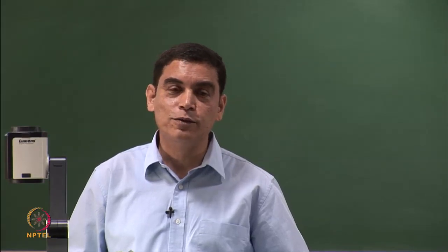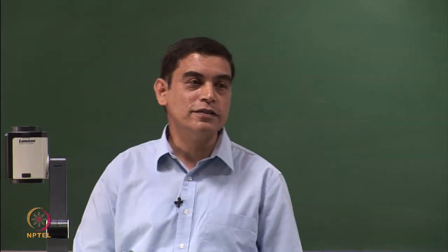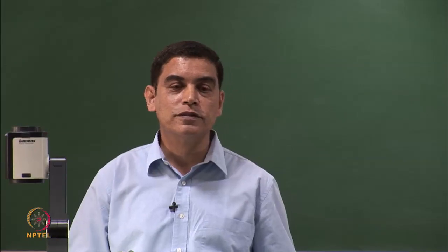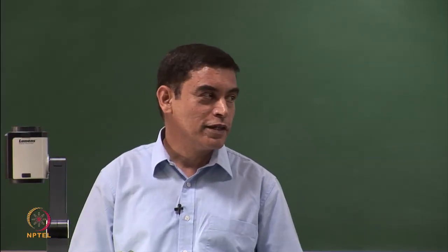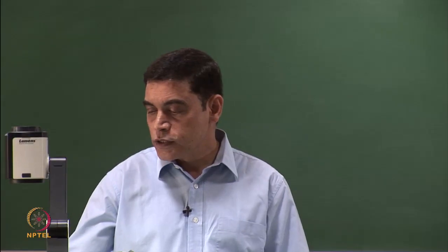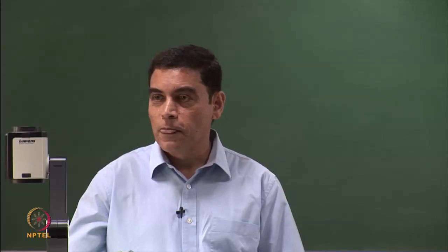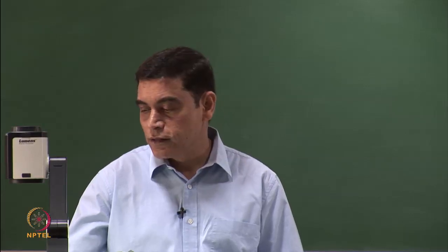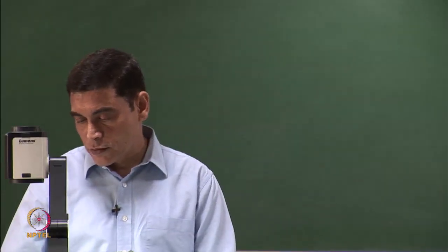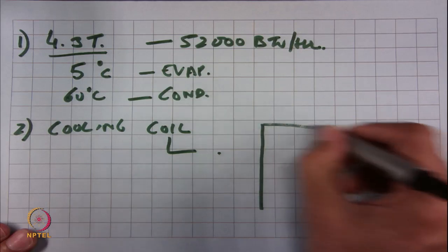So what was available to me was existing product designs and some way to scale them up or down based on an application. The closest reference I had was a 3-ton unit, and based on applying scaling and the need to circuit balance, we made a coil design which looked like this.